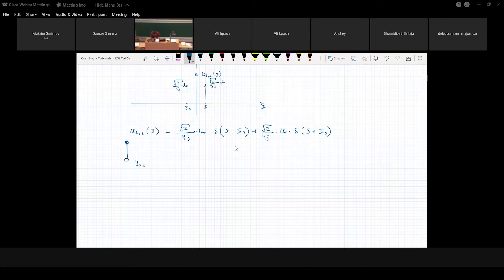But be careful, because for a cosine function you get two delta pulses with magnitudes 1 over 2. So we split this scalar in front of the delta pulse and rewrite it as square root of 2 over 2j times 1 over 2. This 1 over 2 goes to the delta pulse, and we don't have it anymore. What will we have left?